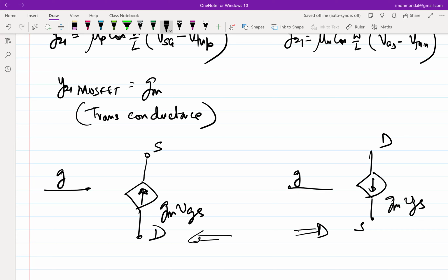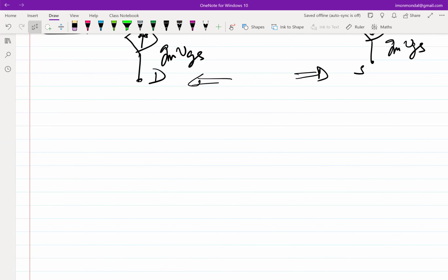Okay, so now that we have a complementary device, which essentially means that whatever we could have done with the PMOSFET, we can do with the NMOSFET, right? So then what I would like to focus on is, given that we know how to design a common source amplifier using a PMOSFET, how do I go about designing the same amplifier using an NMOSFET? I don't want to start from scratch, right? I already know how a common source amplifier using a PMOSFET works. I would like to import the existing knowledge into NMOSFET. Okay, so let's do that.